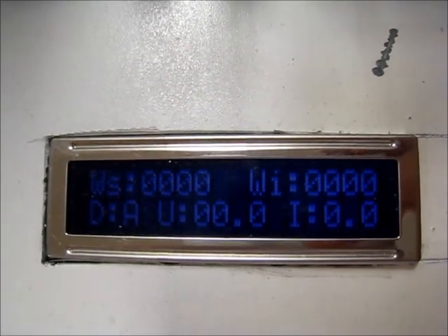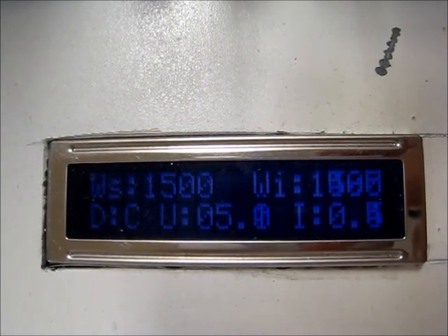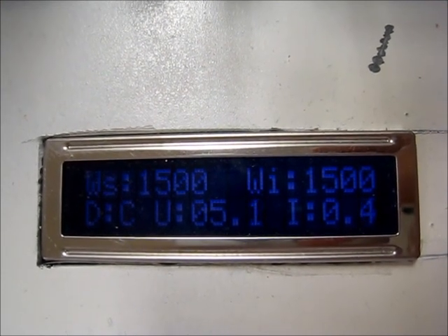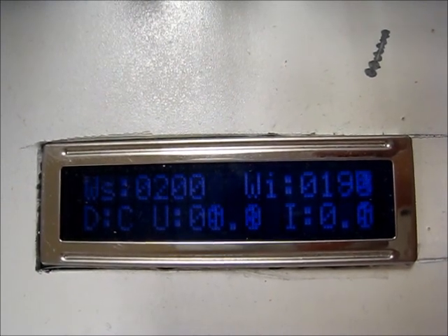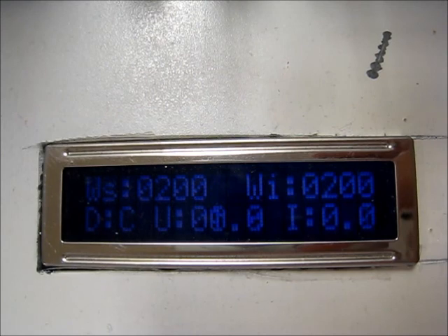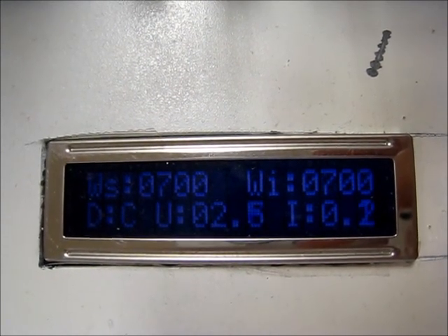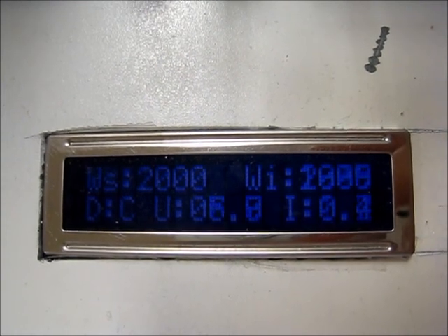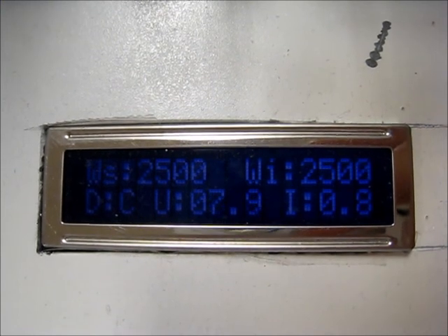Now see the system running with set point, actual speed, direction, voltage and current. At the normal speed of 1500 revolutions per minute, you can see that there is no steady state error. One feature is that you can choose different set points in steps of 100. In this case 200, 700, 1500, 2000 and 2500 are chosen to show that the controller works well for every speed. At low speed, the bent shaft has a higher influence because the bending frequency is lower.